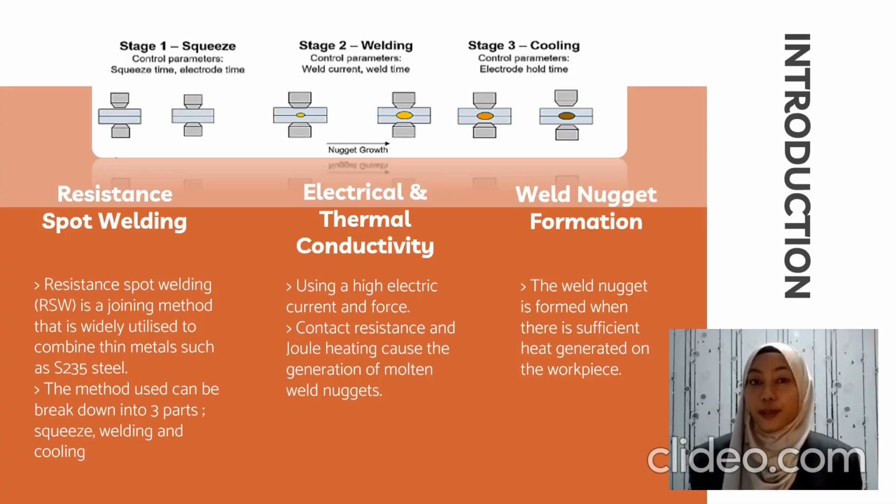To start, resistance spot welding techniques have been employed in a variety of sectors for over a century. Over time, the process has evolved into a standard and popular method of combining thin metals such as steel sheet and steel sheet. The spot weld procedure is used not just in manufacturing industries such as automotive, but also in aerospace and also packaging. Spot welding is most commonly used to join parts that are less than 3 mm thick, and it is less effective if the thickness is greater.